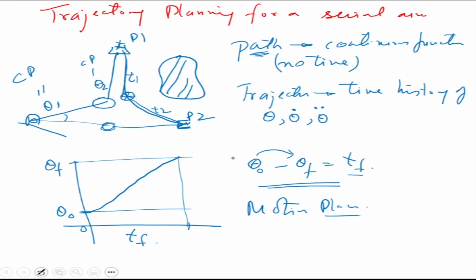So today we looked at the basic search algorithms, that is, how do we search given a network of paths. After we find the best path, then we have to go on the path. In the case of a mobile robot, the robot has to be actuated to go on the path. In the case of a manipulator, given the end effector path, you may have to find the joint trajectories by fitting a cubic polynomial. So we'll stop here and then continue in the next class.